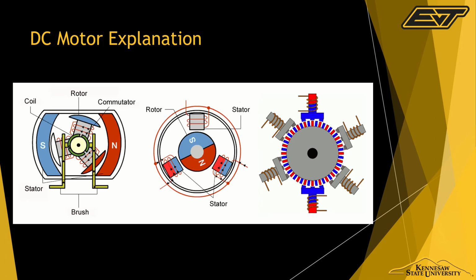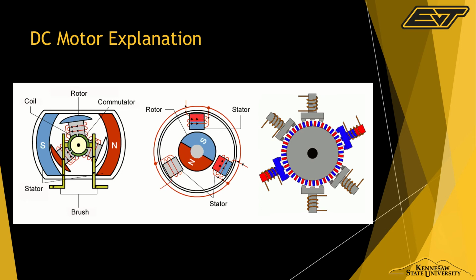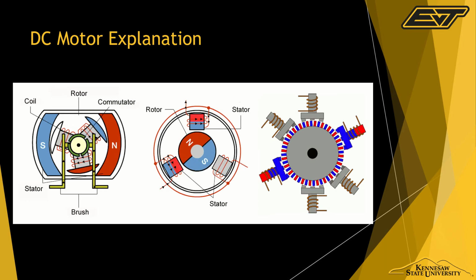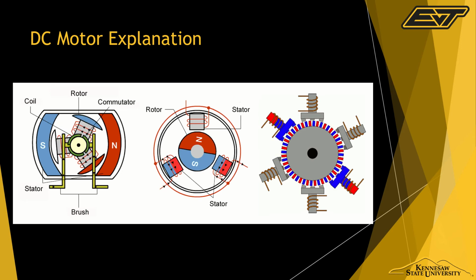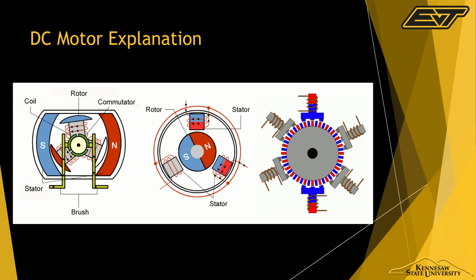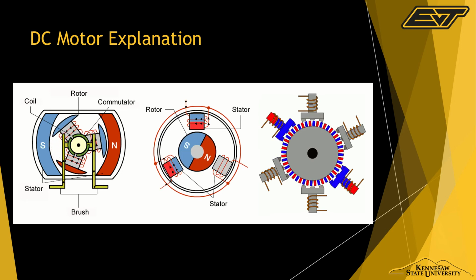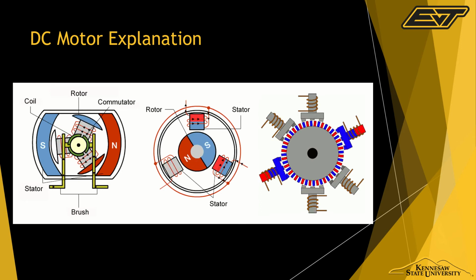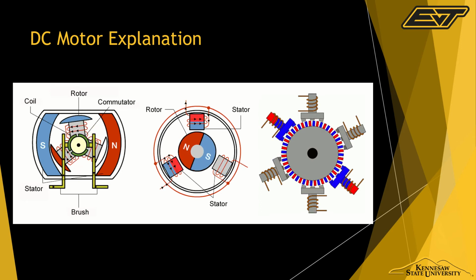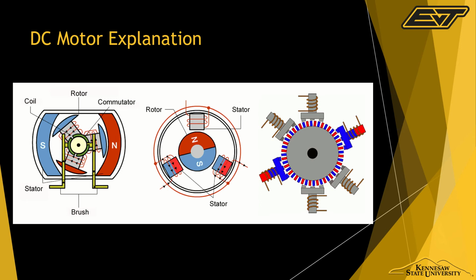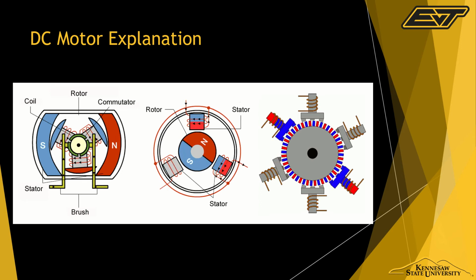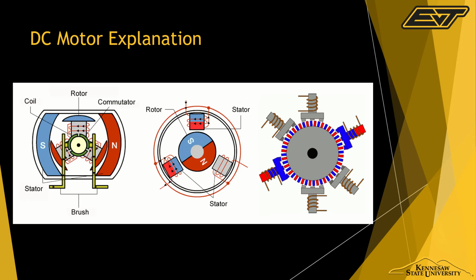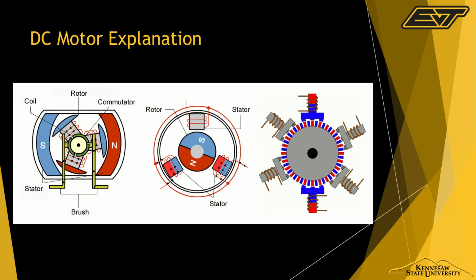That is a Y configuration, which we're going to go into later. And you'll see that it uses current going in both directions. In order to drive up the efficiency, instead of using a square wave, you can use a sine wave, and then technically it would be a three-phase AC motor. So I don't know why people even call these a DC motor, but that's what they're called.